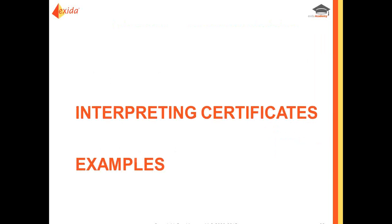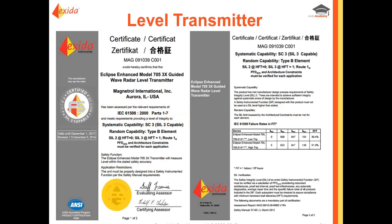I always learn best by examples, so I pulled different certifications to get some different examples for you. The first example we're looking at is a level transmitter. If we take a look, the first thing you see on the bottom left-hand corner is our ANSI logo, and above that you can see this was evaluated per IEC 61508, and it is SIL 3 capable.